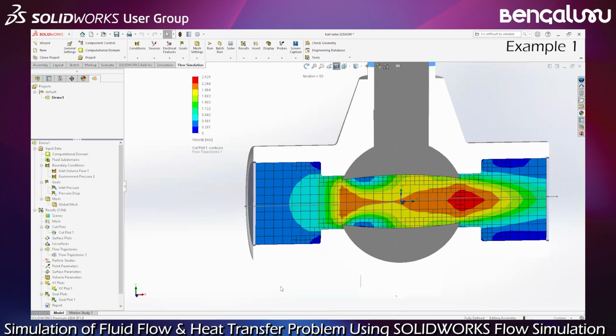And at the end, again, if I am in the design process, early in the process, I don't need to do this. Okay, the automatic mesh is good enough. Now, if I want to validate, let's say it is my final design, and before manufacturing, I would like to do an accurate simulation. Okay, so for this, of course, we need to change the mesh.